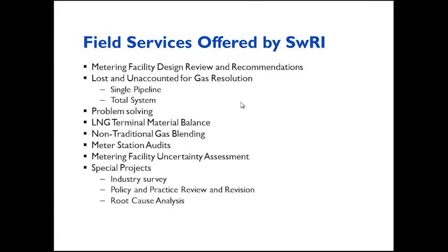Oftentimes what we get in terms of definition from the deal makers and instructions to the engineers don't fit well with that particular concept. And then it needs to be appropriately assigned for the application. If you're constantly operating on the bottom 10% of capacity, you're never going to get good measurement results, and you're likely to have arguments with your customers.